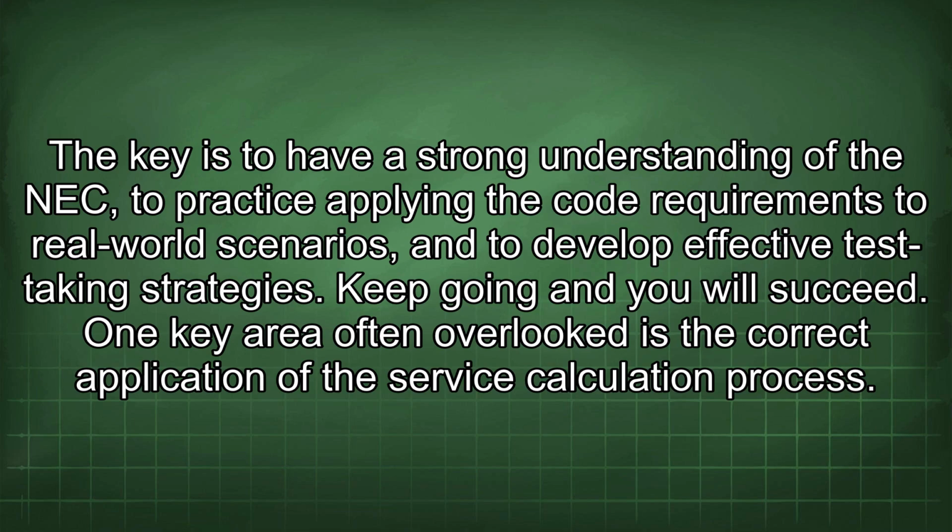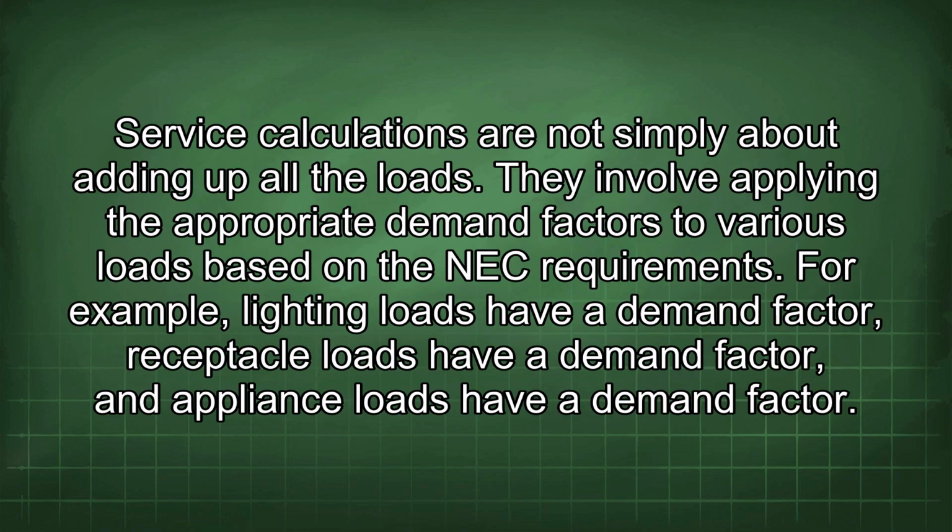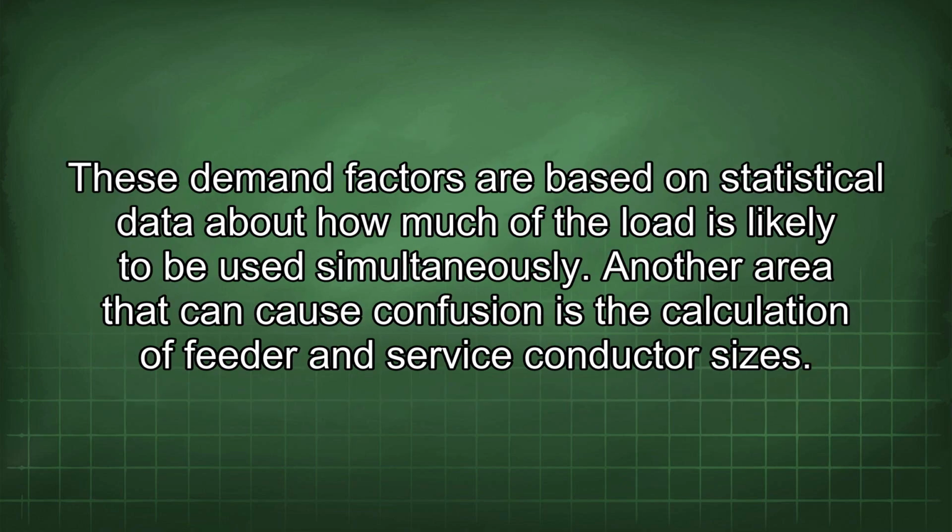One key area often overlooked is the correct application of the service calculation process. Service calculations are not simply about adding up all the loads. They involve applying the appropriate demand factors to various loads based on the NEC requirements. For example, lighting loads have a demand factor, receptacle loads have a demand factor, and appliance loads have a demand factor. These demand factors are based on statistical data about how much of the load is likely to be used simultaneously.